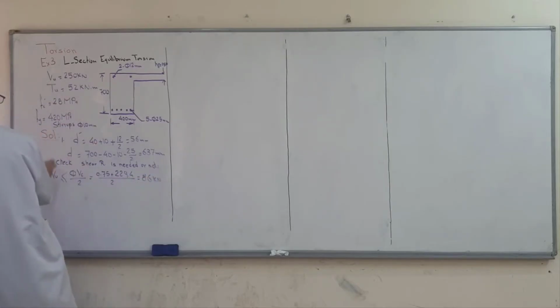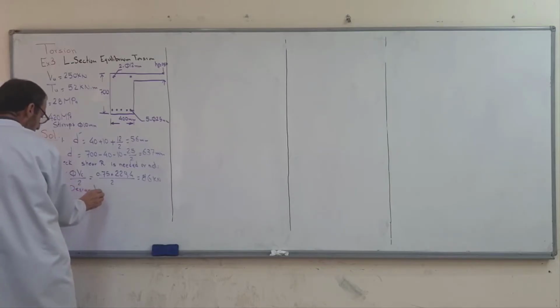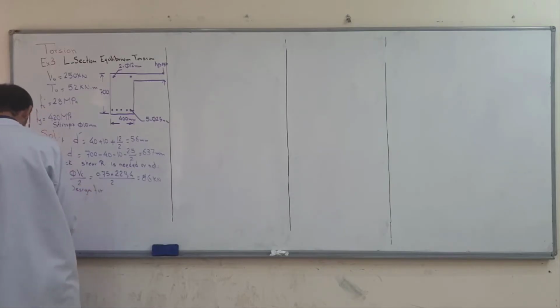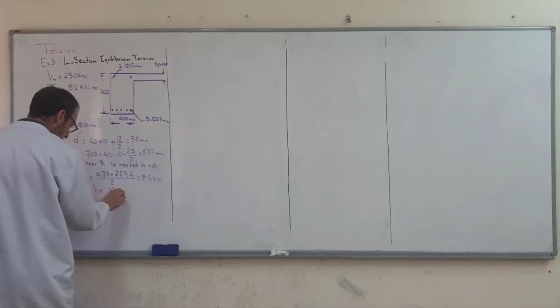Applied V ultimate is 215. Therefore, design for shear reinforcement is required. Design for stirrups is needed.